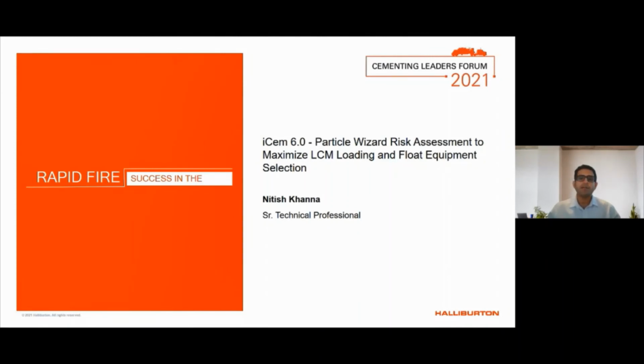This morning, I'll be discussing a case history wherein we utilized the Particle Wizard risk assessment tool in iCem to design and validate loss circulation and well life material loadings for both spacer and cements. Now, LCM is typically added in spacer and cements to cure losses and achieve a desired top of cement.